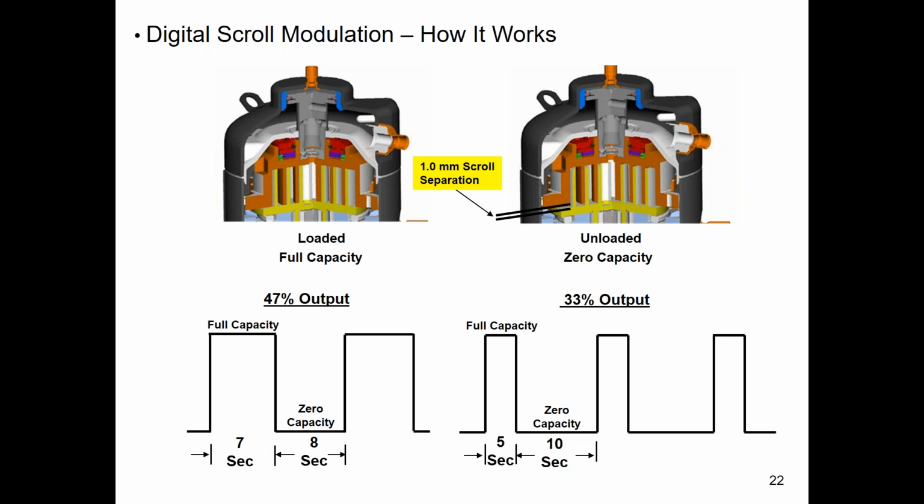Well, it's migration. Refrigerant always seeks the coldest location in the off cycle. So if you think about your condensing unit being out in the ambient, could be a 70-degree day, we probably have 70 degrees across the evaporator indoors or more. And so the coldest spot is going to be the refrigerant piping that's underground, which typically ground temperatures are anywhere from 52 to 60 degrees, depending on where you're at. So the refrigerant's going to migrate down to your pipe.